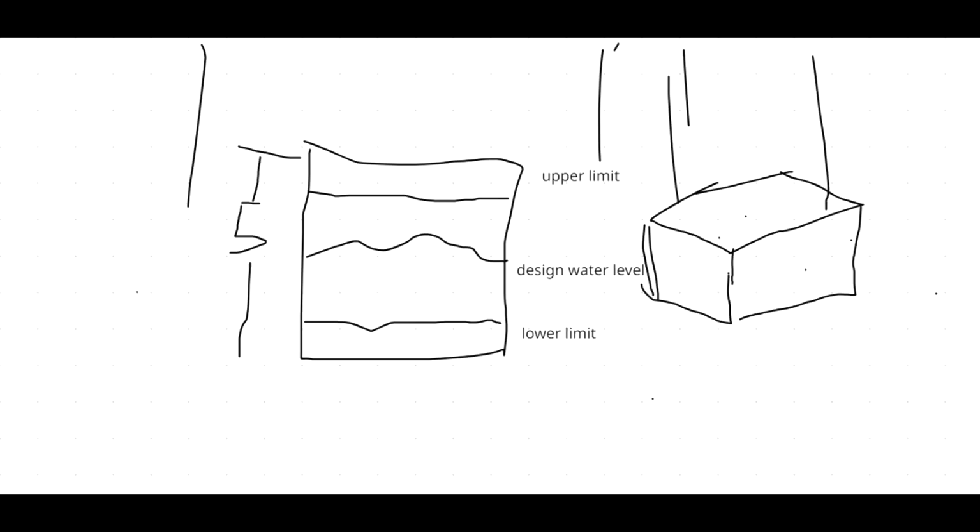So that design water level, you now add it to the height of the stanchion. Let's say the stanchion is 6 meters, and the design water level now is 2.5. You now say 2.5 plus 6 meters. It will now give you 8.5 meters. You get the point? It is that 8.5 meters that you will now use as your water height of tank, and not using 6 meters or using 11 meters. Okay? 6 meters is the lower, 11 meters is the upper. So you use your nominal, meaning at every point in time, I assume that if water is at 8.5, I can balance my system.